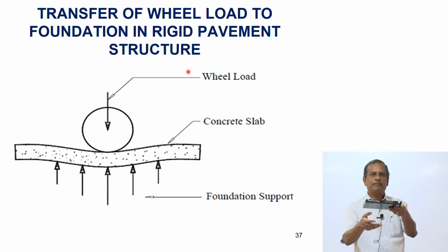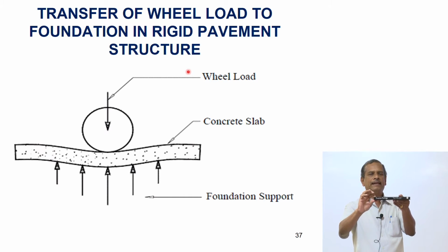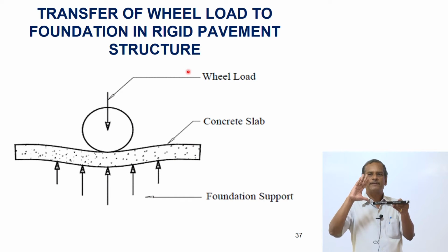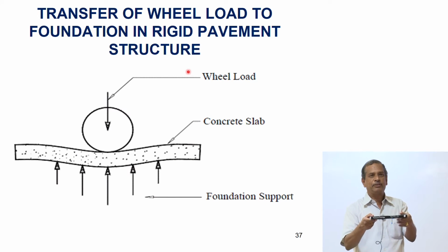Even if the subgrade is weak, I can provide a rigid layer and reduce the thickness of the pavement layers. So I need only one layer of concrete, maybe over a base course. So the total thickness of the pavement is much less. This concrete pavement will last for 30 years without major maintenance, but the initial cost is higher than a conventional bituminous pavement.